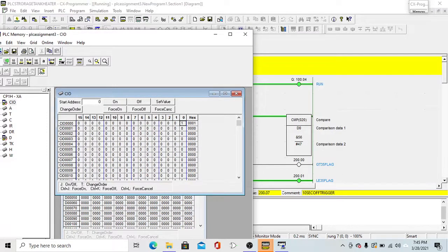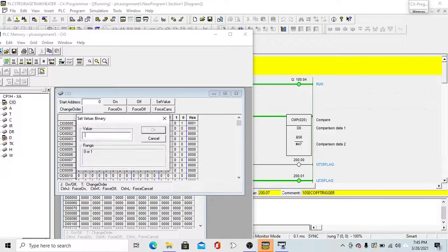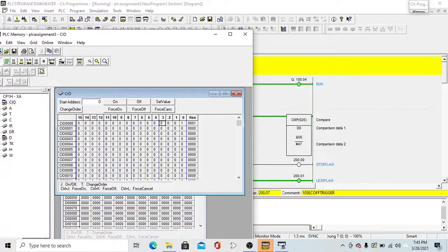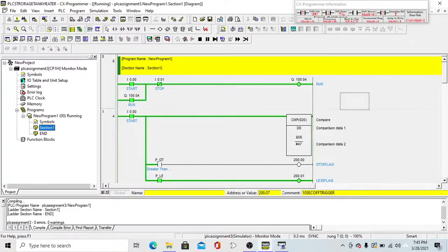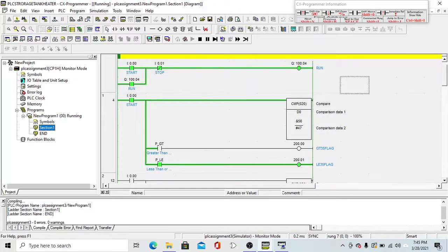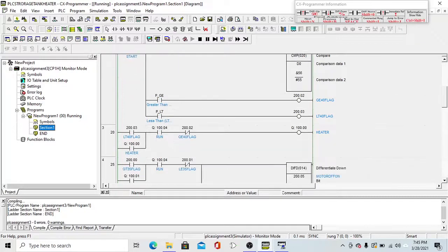We're also going to set the, let me just make sure I'm telling you the right thing. Yes, we're also going to set the lower level switch to 1, which is located at register 3 in that row. Alright, so we expect, based on the problem definition, that valve 1 should turn on and the heater should turn off. So you notice it says run, so that means the system is on. Let us see.